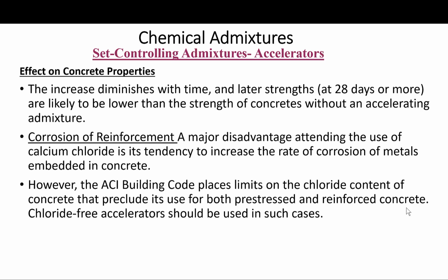But the ACI building code places limits on chloride content of the concrete that basically preclude its use for both pre-stressed and conventionally reinforced concrete. There are other chloride-free accelerators that exist, which should be used in such cases.